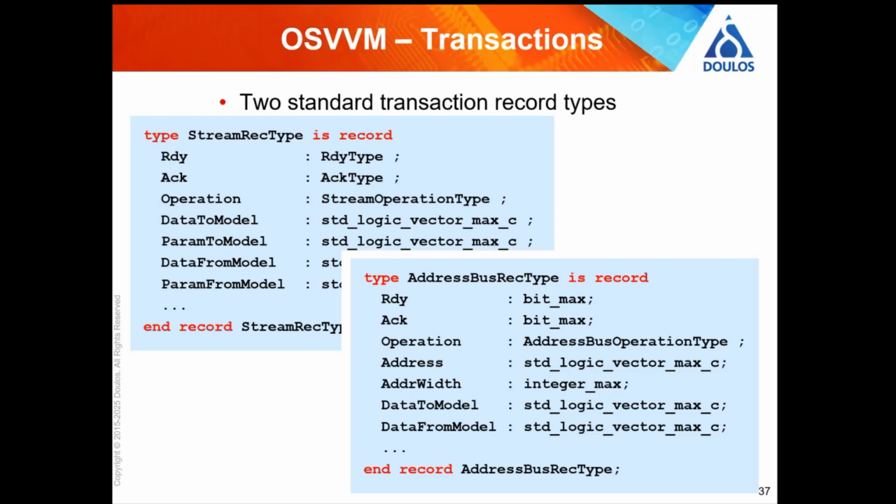And notice, this is a VHDL methodology, so the code I'm showing you now is VHDL. Instead of calling a procedure to represent a transaction, we're using a VHDL record type. So a different software engineering construct is used to represent this abstract thing called a transaction.